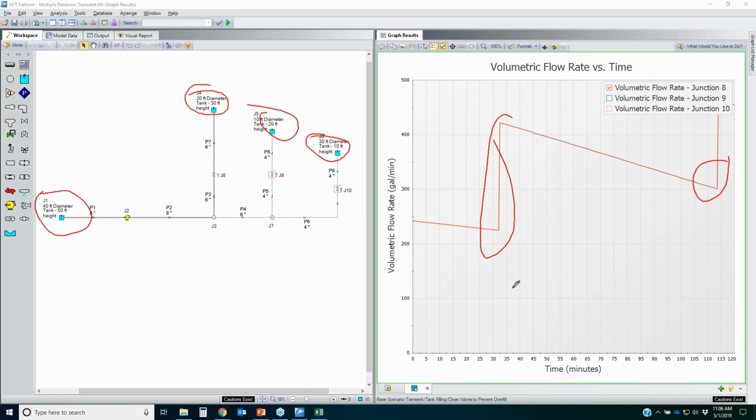And you're not going to be able to get a good idea of what the actual flow distribution would be, nor would you know how your flow rate through the pump changes over time. So rather than doing a whole bunch of separate steady state runs and throwing those aggregate results into Excel, just use the XTS module and you'll make it so much easier on yourself.